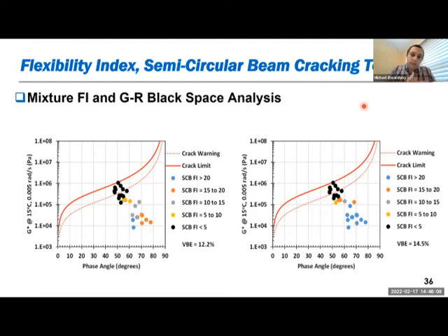We're not just talking about the binder quality, but how the binder quality could affect our mix design. We would like to look at balanced mix design more as a 3D thing, looking at not just binder content and trying to adjust binder content between fatigue cracking and rutting, but actually trying to capture also, or put in this equation, material selection and binder quality, because this could affect our design dramatically. So we need to think about the bigger picture as well.